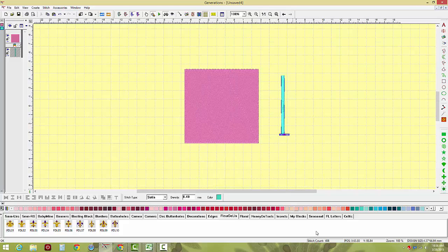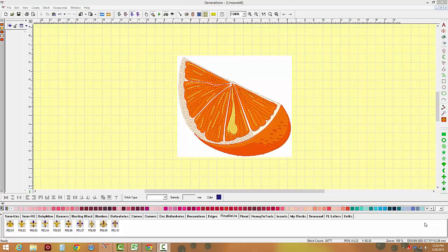If it's a complex fill, no matter what, even if it's on auto judge, you can change that direction. If it's a small area and the program has determined through auto judge that it should be a satin, then you can't change those fill directions unless you use the satin editing.